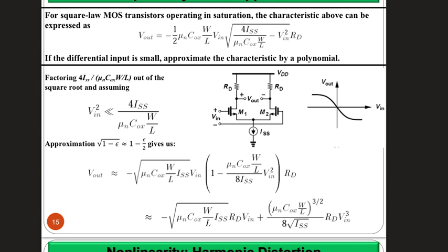If your input signal is with high value, so for example, it starts from here, and it goes up and down, right? And then you want to see with this input-output relation how it would look like in the output. Now what do you do with using an input-output relation? You project and then you project in the other direction, right? Now if you take this signal and you project it here, and then you project in the other direction, you will find that at the output, it really varies over a very small range, right? So it's gonna be something like this. So rather than amplifying, you ended up compressing the signal because the amplifier is no longer functioning.